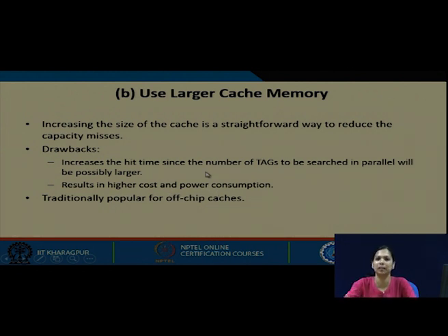Of course, we know that cache memory is built using static RAM, which requires roughly 6 transistors for 1 bit. So, it is much costlier compared to DRAM. If you are increasing the cache memory, you are increasing the cost as well. So, all these are related. Which one you will reduce and by how much, such that you get a better gain in turn, is a parameter that needs to be analyzed and understood.